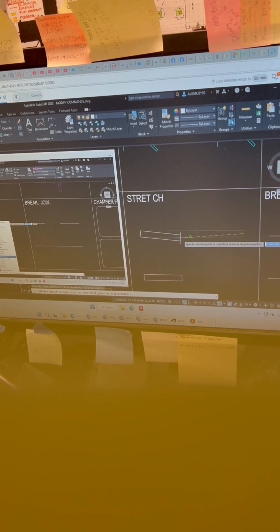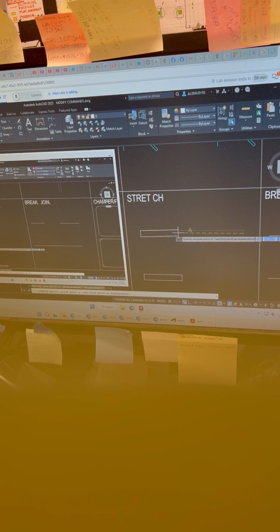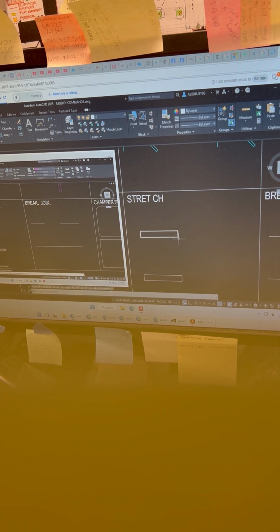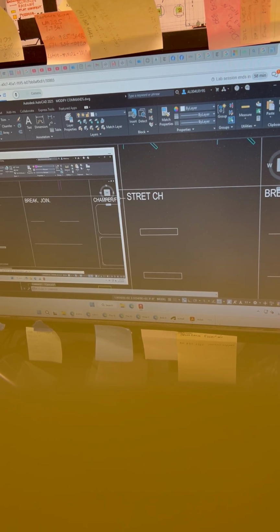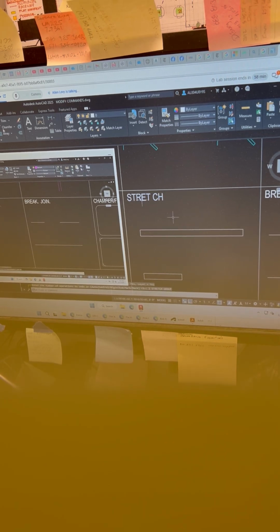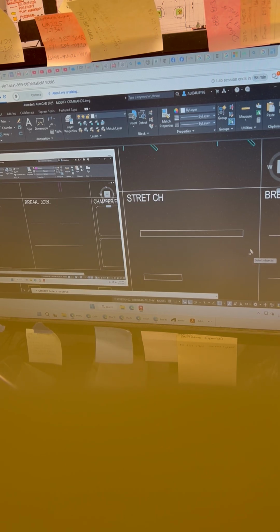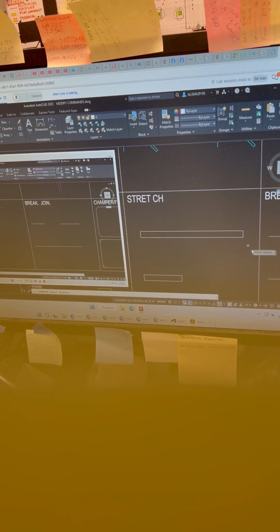When you do that, I want you to hover over this end of this guy right here, and look above, there's the perpendicular snap. If you click on that vertical edge of that object below, now you can stretch that thing, and it's exactly the same length and perpendicular to the edge of the other one.